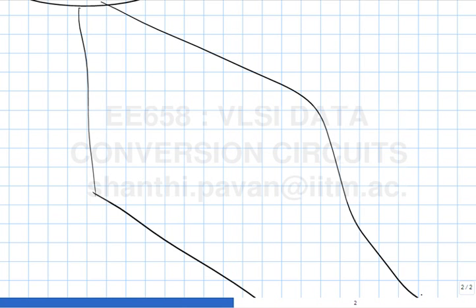This is definitely an idea which will get rid of it. This is like dipole moment, right? If it is so far away, it only goes as 1 over r square rather than 1 over r. This is the same argument, isn't it? So, some poor soul has to drive all this capacitance if you run long wires, right?